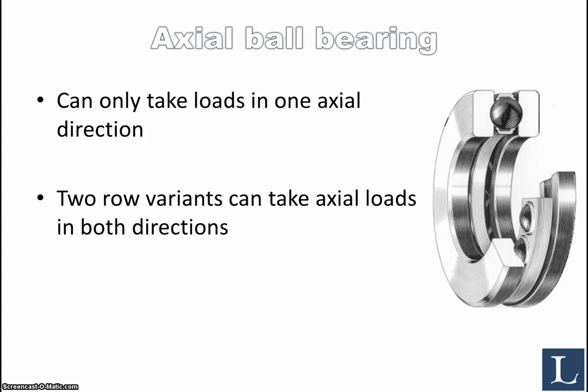For purely axial loading, there is the axial ball bearing. It can only take loads in one direction, in this one shown here. If you have a 2-row axial ball bearing, it can take loads in both directions.